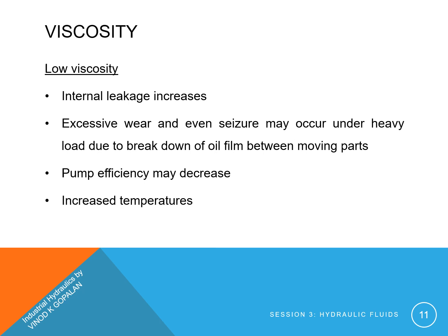Second point is excessive wear and even seizure may occur under heavy load due to breakdown of oil film between moving parts. If the oil viscosity is low, then the oil film formed between the moving parts and the oil seals will be very thin, and that is the reason why this will break down under heavy load.